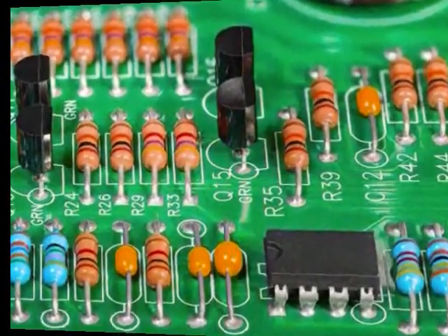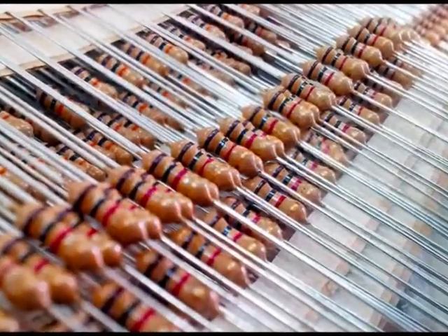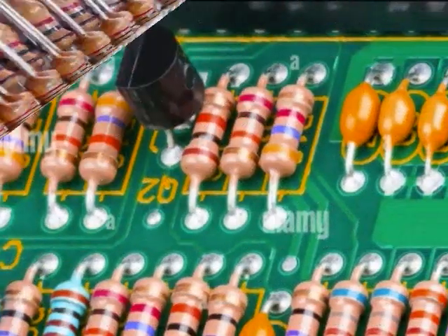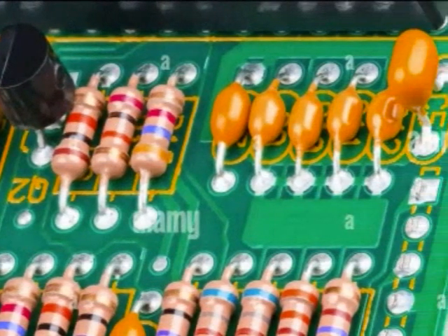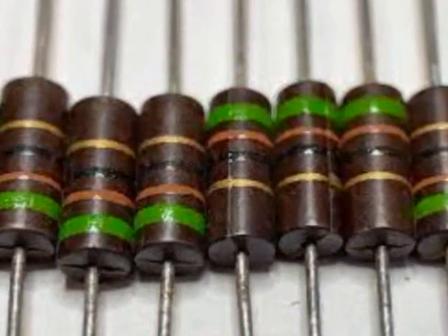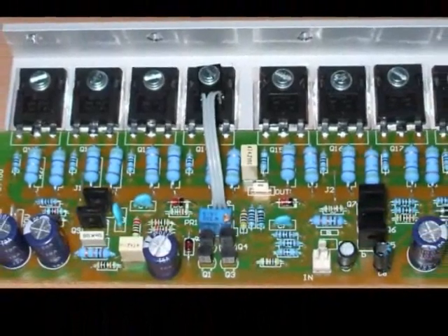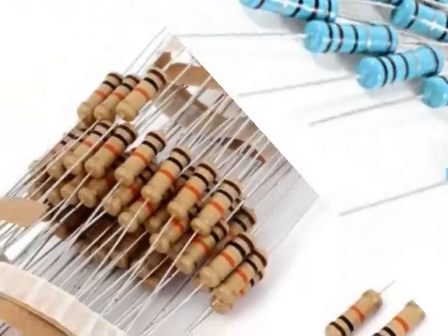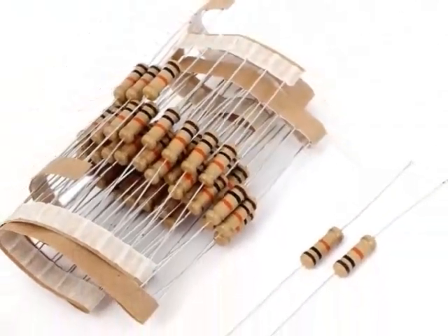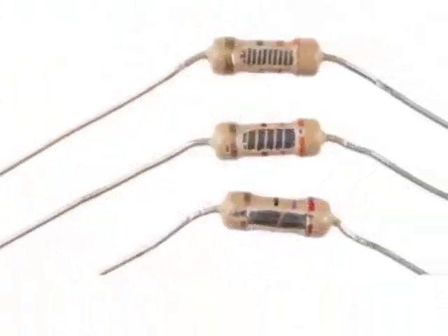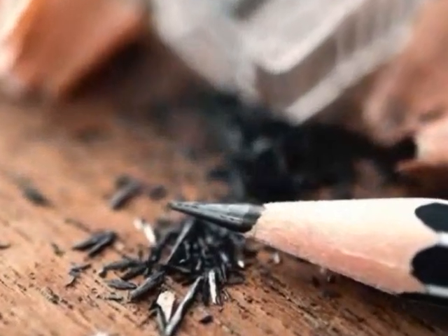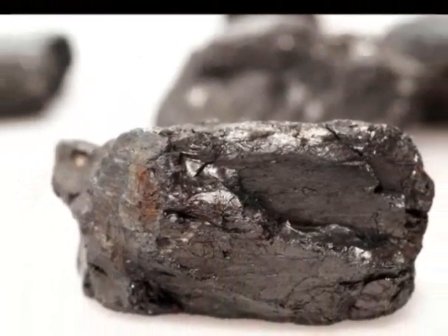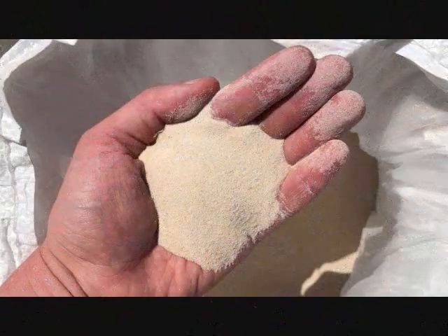Carbon resistances are the most widely used and cheapest types of composite resistances. These resistors are widely used in electronic and electrical circuits. The internal element of these resistors consists of carbon powder or graphite, like the tip of a pencil. Also, in their composition, non-conductive ceramic powder, clay, is also used to stick the carbon round.